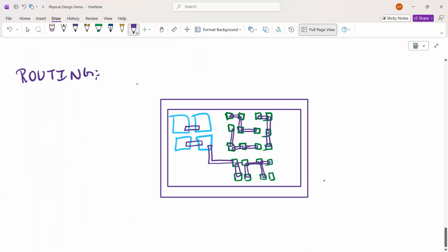Understand that this is the main purpose of a physical design engineer. The flow is already there: placement, CTS, routing will happen. They have the script and will give it to you, and you will run it. But the issues you face, you have to analyze and fix yourself. That we are doing here throughout the flow, analyzing and giving the fixes.